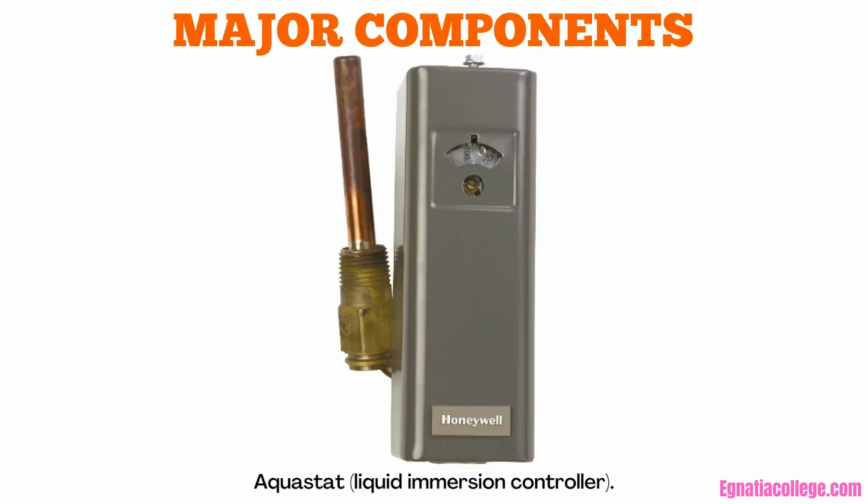Major components. Gas-fired and oil-fired warm air systems and hot water boilers contain many components. Aquastat. This direct immersion water temperature thermostat regulates boiler or tank temperature in hydronic heating systems, ensuring that the circulating water maintains a satisfactory temperature.